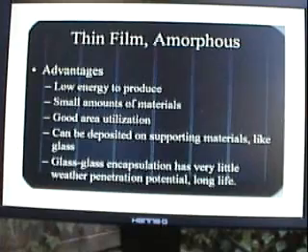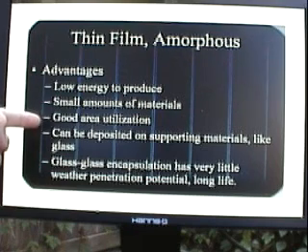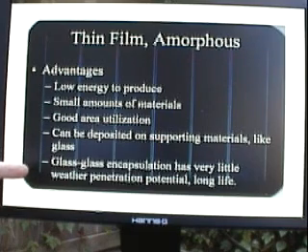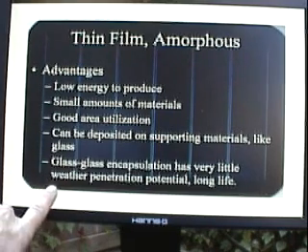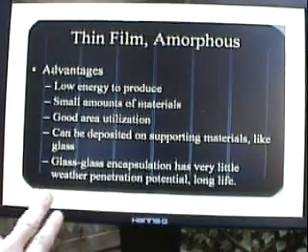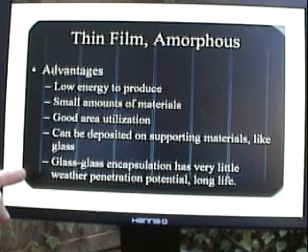So then there's thin film amorphous. A lot less energy to produce, and smaller amounts of material are used. It's got good area utilization and can be deposited on various kinds of material like glass. Encapsulation has a long life because the weather can't get in. If you have a glass sandwich, it's just around the edges where the weather can penetrate.